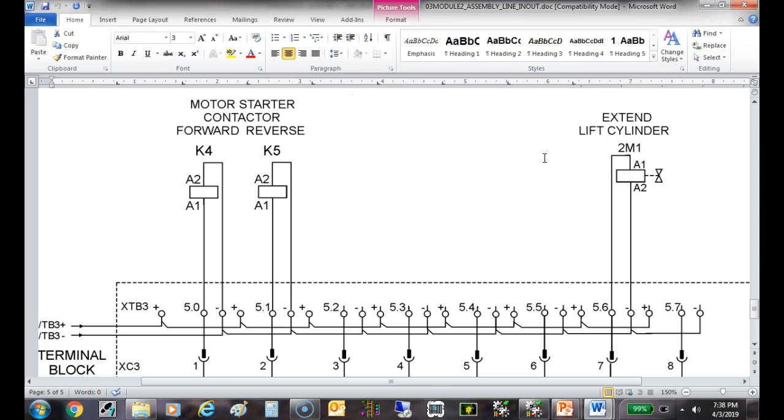Because the ISO symbol, so in motor controls, we say a relay coil is round. The ISO symbol for a relay coil is this triangle, this rectangle, right. Now I know it's a relay coil because it's labeled K. K means relay. It's the coil of the relay. And this is standard. K, you see that used all over.